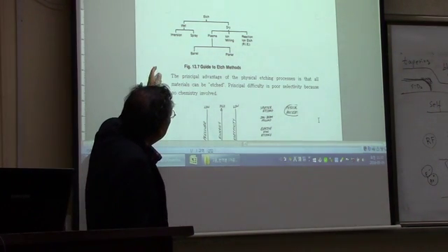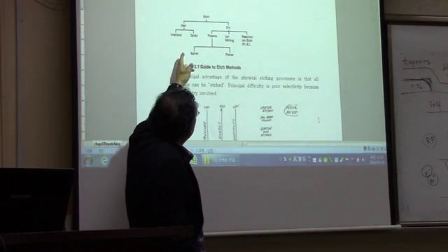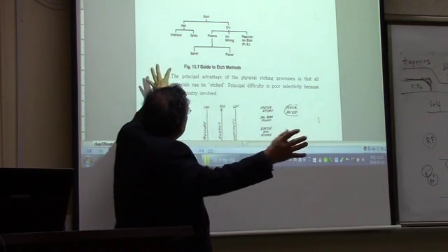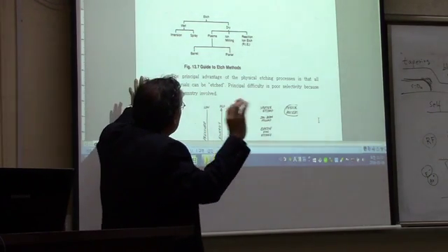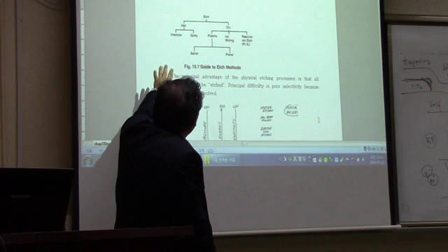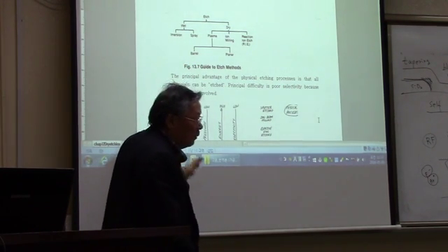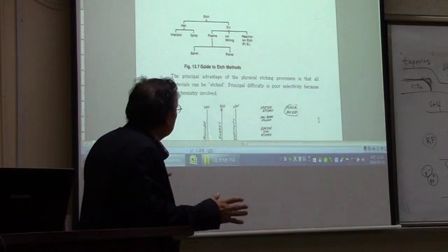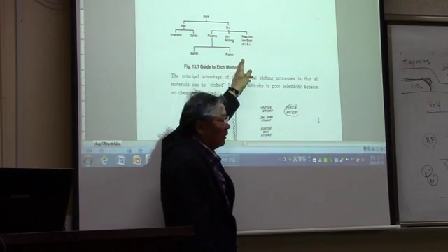Okay, we summarize the etching process. We start out with the distinction between wet etching and dry etching here. Wet etching is isotropic, so dimensional control is impossible with wet etching. So that's why dry etching has been developed.